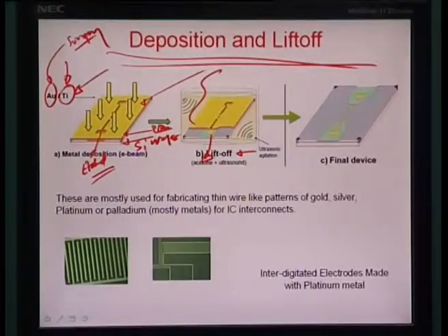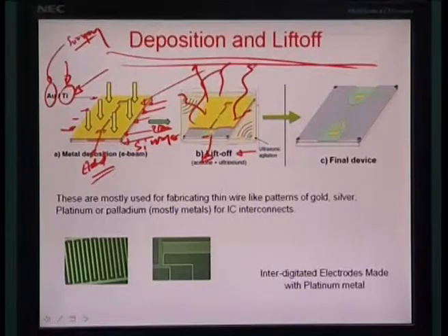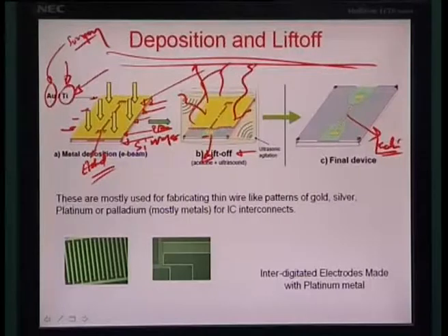liftoff. So, whatever photoresist here can be laterally etched using some kind of solution like acetone, etc. However, the portions which are adhered more firmly onto the silicon substrate remain, and the other layers of the photoresist go off because of the development. So, this process is known as liftoff. Finally, you are left with a feature or a conduit made up of metal on the silicon wafer. So, you have an etching process followed by a deposition and liftoff process here.